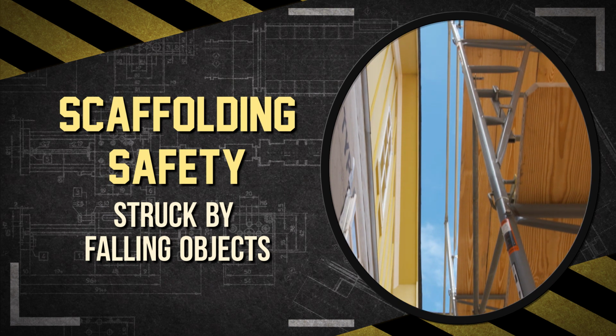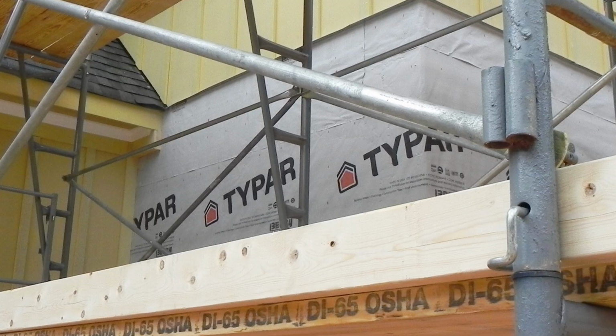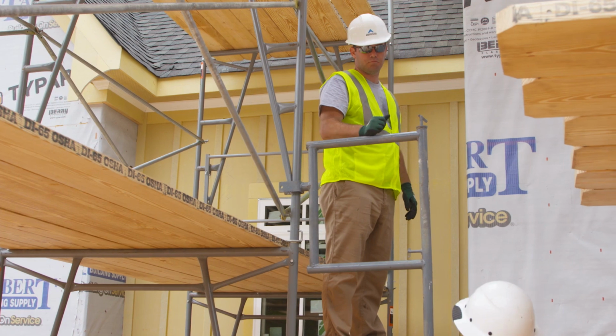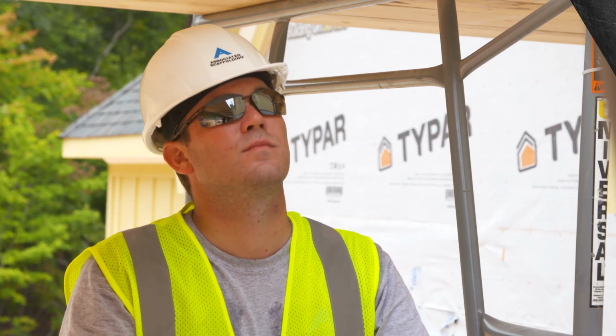Being struck by falling objects is a common occurrence that can be reduced or eliminated by using toe boards, netting, or by barricading the area. It's important to note that hard hats must be worn at all times when working on and near scaffolding.